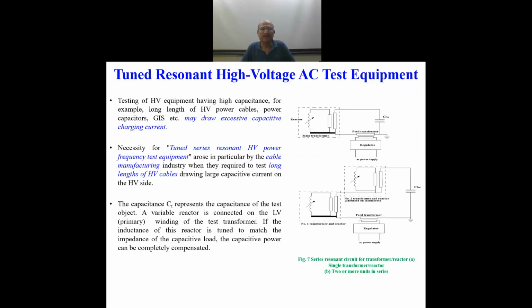So when, for example, just think of 500 kV polyethylene cable, which requires something like 2.8 centimeter thick insulation around the conductor in a single core. And if you have to test, say, 500 meters of such cable, you can calculate it. So very high capacitance formed by the cable. And when you apply to the tune of 500 kV, you may need 2.5 to 3 times U0. We talked about U0 yesterday. The voltage may be something like 750 kV to be applied.